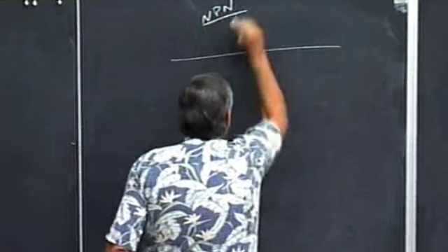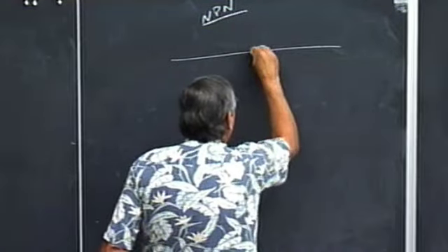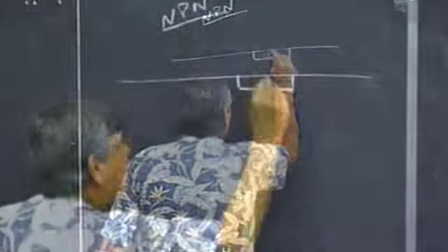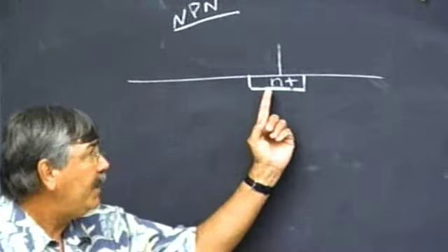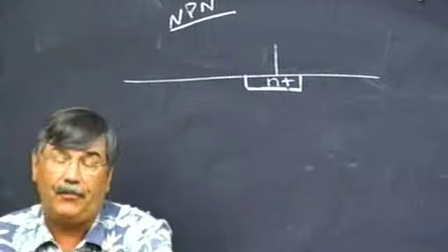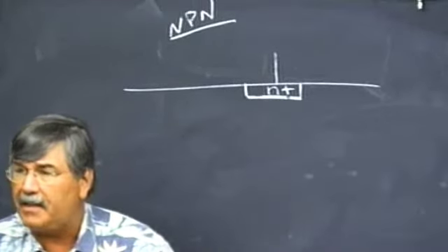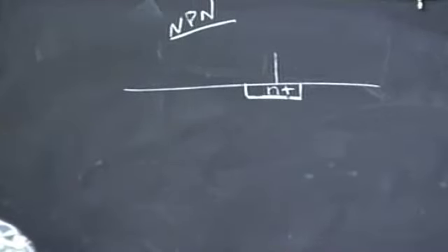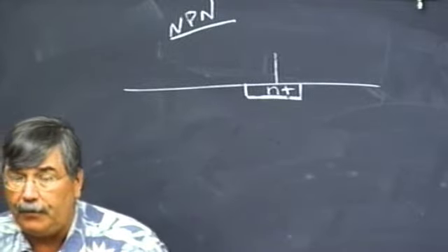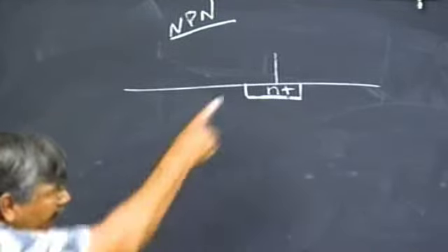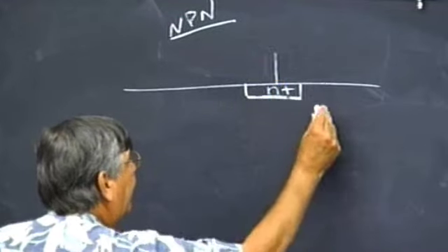So the structure that we usually want is concentric from the top down. Heavily doped N-type is going to form the emitter. When I say heavily doped, I put either N or P with a plus, and that means dope it as heavy as you can, 10 to the 19th or more. When it's doped very heavily, it acts just like a metal. It's very highly conductive. There's lots of electrons in this case, or lots of holes if it had been P+. Okay, so it's very conductive. Anyway, that's the emitter, and we'll make a contact to that.